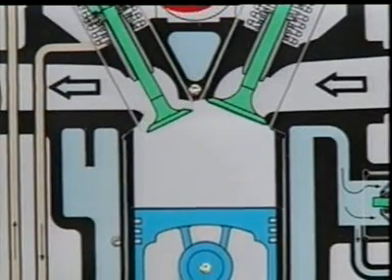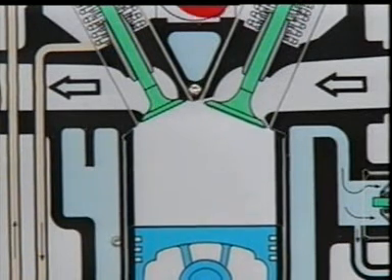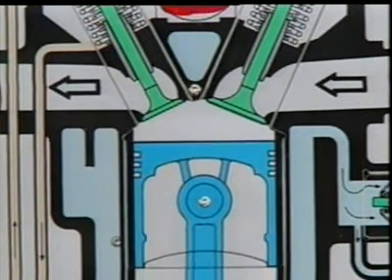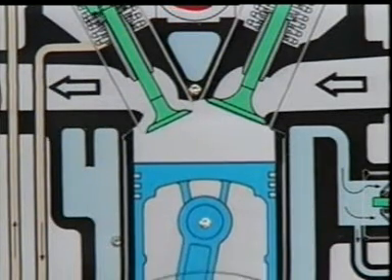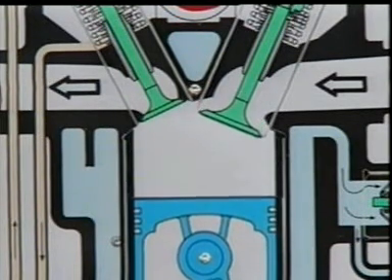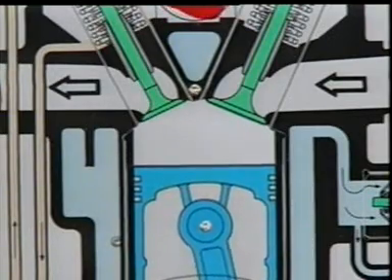If we take a closer look at an actual engine, we can see that valve timing is slightly different from the times when the piston reaches TDC and BDC. The valve timing is set in this way due to the inertia of the mixture and exhaust gases in order to improve engine efficiency.